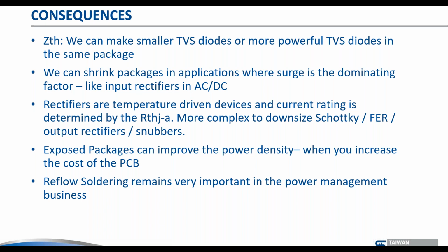So here's another opportunity to potentially do it. Obviously, rectifiers are temperature-driven devices. So if we're really having a lot of current and a lot of power here, it becomes significantly more complex to downsize and to get the heat away from it, and it will depend on your design rather than us. Exposed packages can improve the power densities. We have them available, but you need to increase the cost